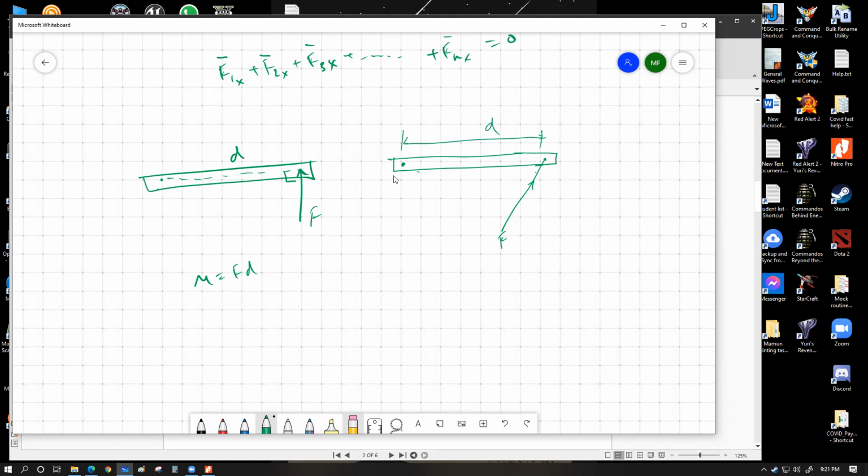In that case we have to draw up a perpendicular line over here, so that this is producing a 90 degree over here, and if the force produces an angle theta with the axis of the object, then this length should be d sine theta. So that way the moment produced should be force multiplied by perpendicular distance of the force from the pivot point, which should be M equals F into d sine theta. So that can also work.